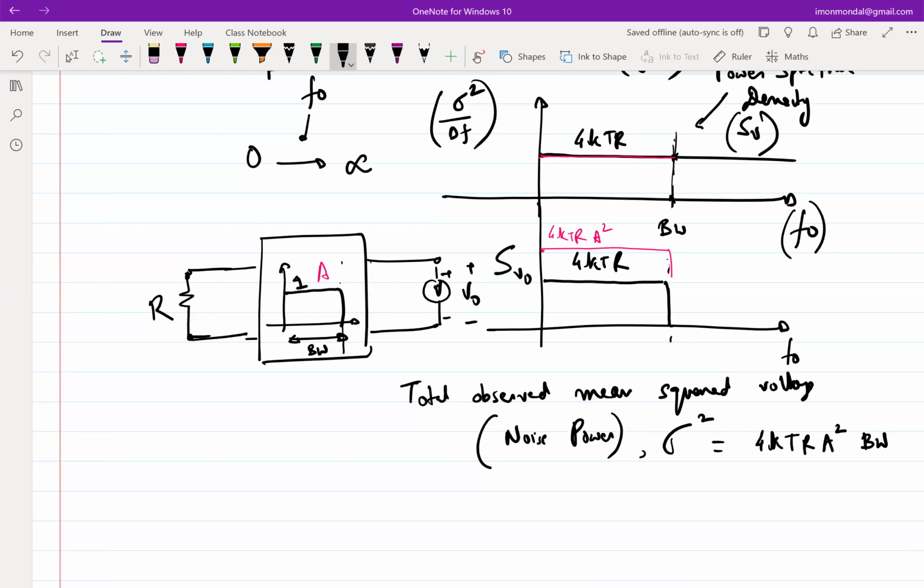Yes. Okay. So, what are the consequences of the total noise power? I mean, with the example of the signal to noise ratio or noise power, we are talking about one particular frequency. We are not bothered about the bandwidth of the filter and all. So if we are bothered about one particular frequency, why should I open the channel for the entire band? If I'm bothered about one small narrow band, one frequency, I will have a filter around only that frequency. I need not open up the entire band.